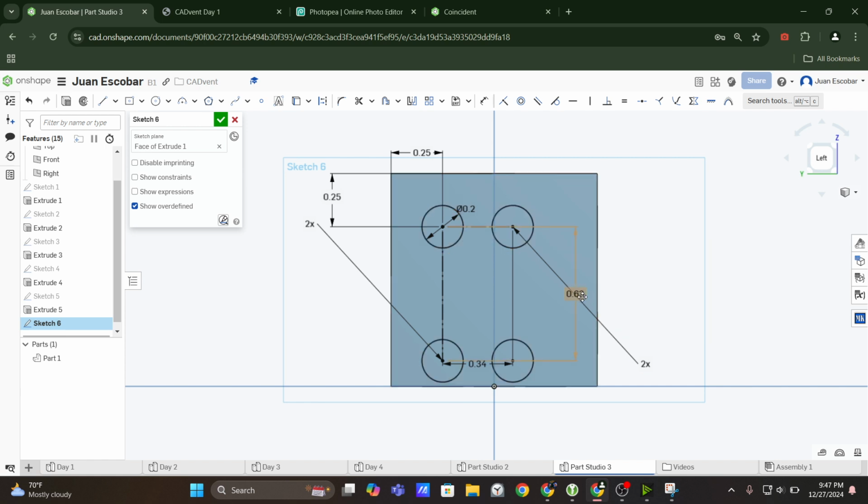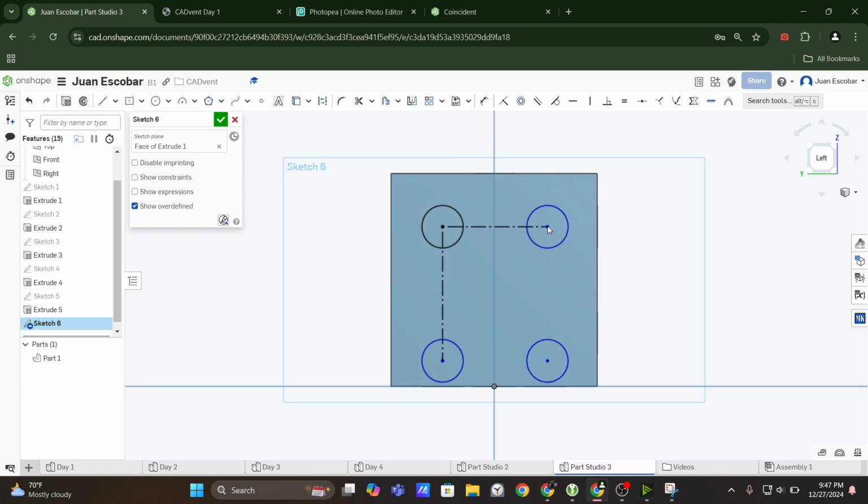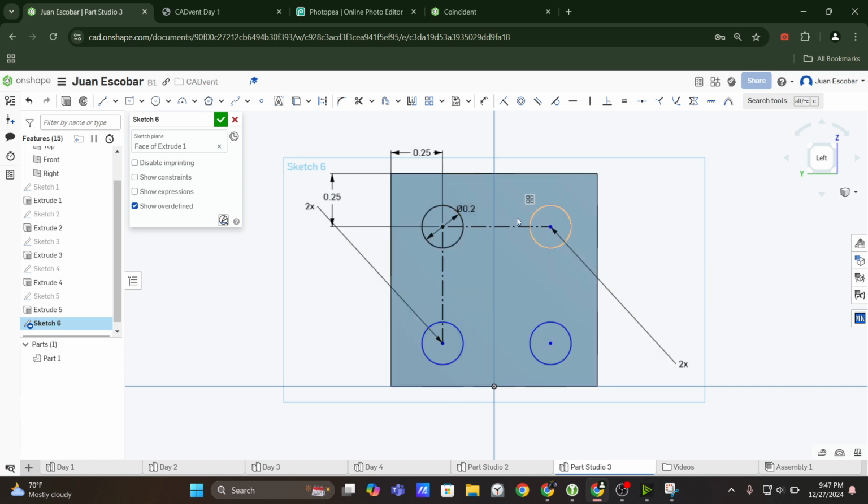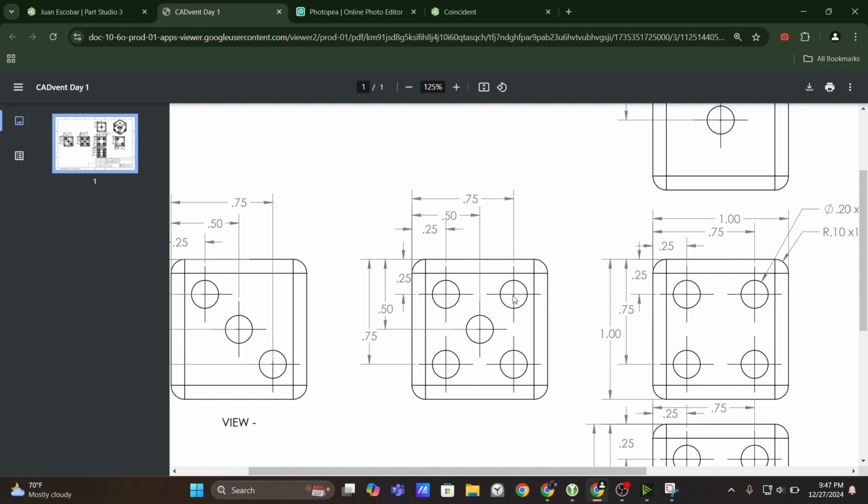And let's say these dimensions are useless. I'll get rid of them both. Just to reiterate the other thing that I said earlier, you don't need those dimensions necessarily. Right now, these are all just defined as they're linear. It's a linear pattern, but you don't necessarily need those 2 dimensions. So I'll just set an arbitrary direction.